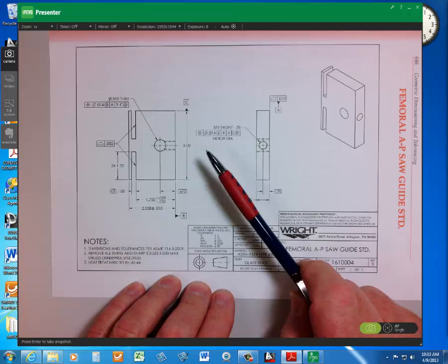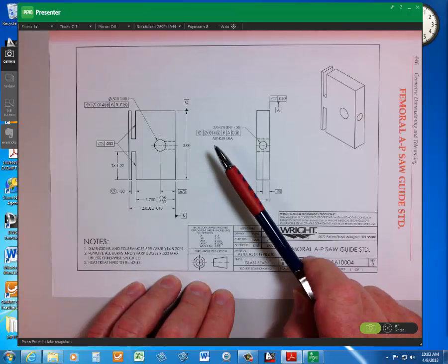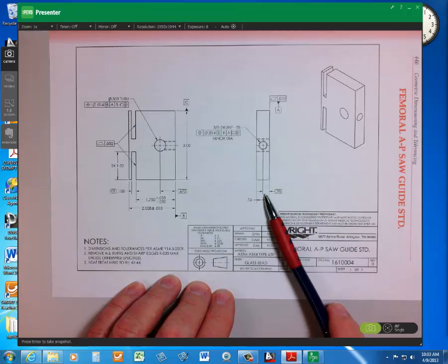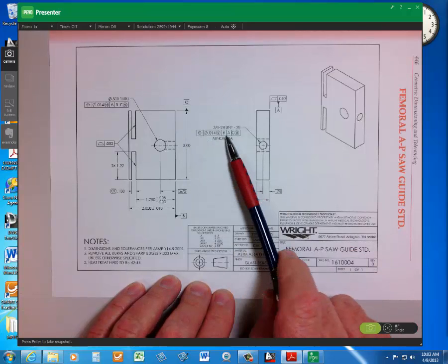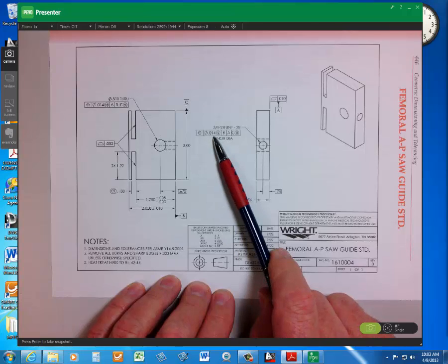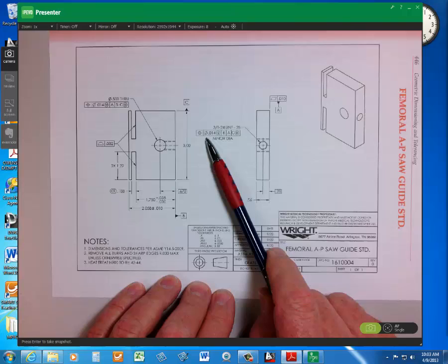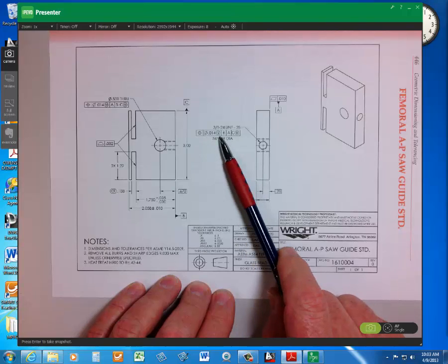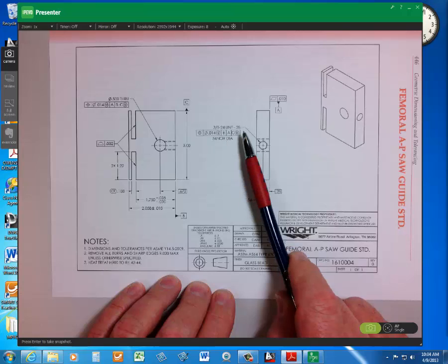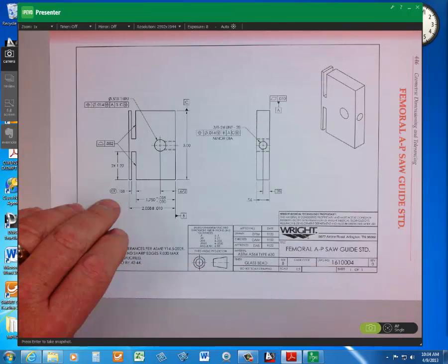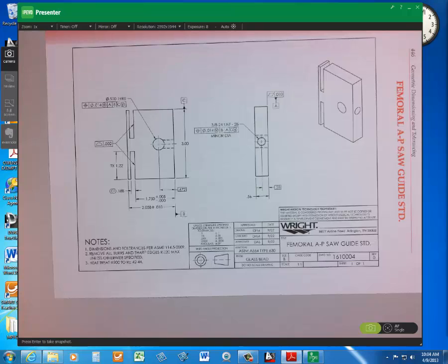So the feature is located 2.8 basic from datum A and on center plane of datum C. And the feature control, reading it, is controlled by cylindrical position, 14 thousandths at max material condition with respect to B relative to A and C at max material boundary.